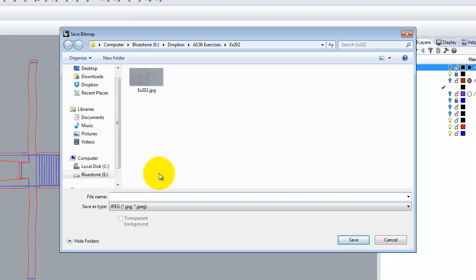If you struggle with trees showing up in the skyline or whatever, change your HDRI background image or put yourself lower at more street level and do your rendering looking up, which will hide all of those trees. We will deal more with how to hide those trees when we do the final project and the renderings there. So there are ways around it, or there's HDRIs that are better than others to pick. But for right now, just change your camera angle to miss them. So for 203, you do need to do the unrolled surface and you need to do the rendering. So it's kind of a conglomeration of everything we've been doing.